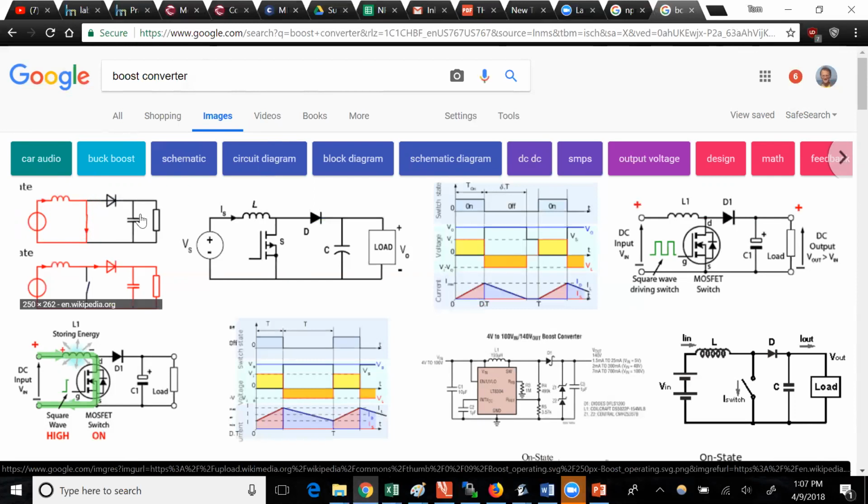And inductors make a big spike when their current shuts off suddenly. They don't like that, a big voltage spike. So that voltage spike will actually exceed the voltage of your power source, and so it will get a higher voltage on the capacitor than you have on your voltage source. And then once you close the switch again, you're recharging the inductor.